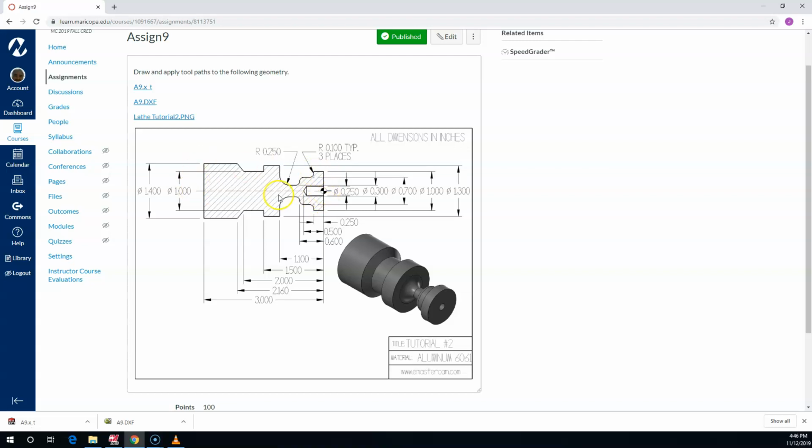So drawing the rectangle, setting up the physical boundary, doing the offsets. One of the things I was looking through last night that I didn't realize was the line parallel. I've seen it before, and it was one of those, hey, what does that do? Line parallel is basically the exact same thing as offset. It's just right next to your line commands. So we'll look at that one.